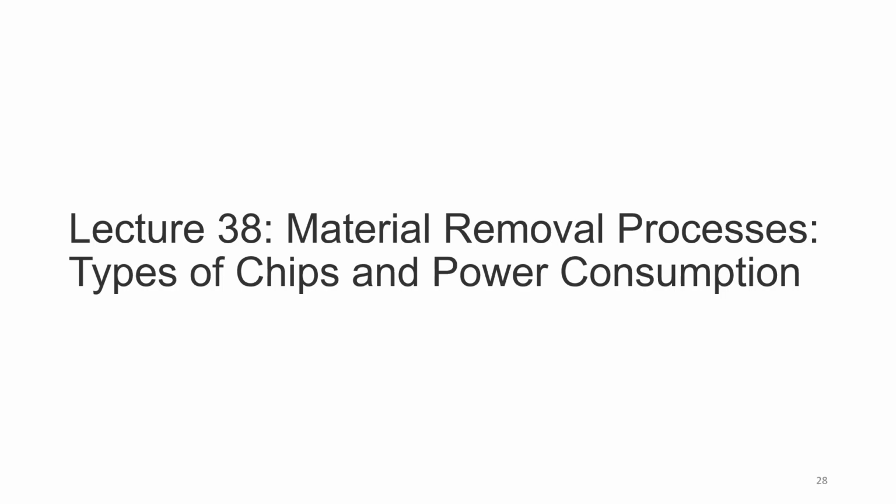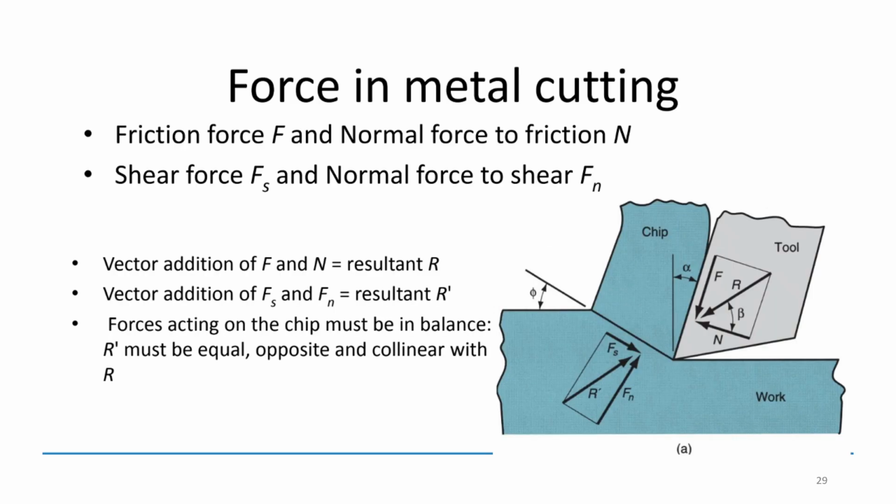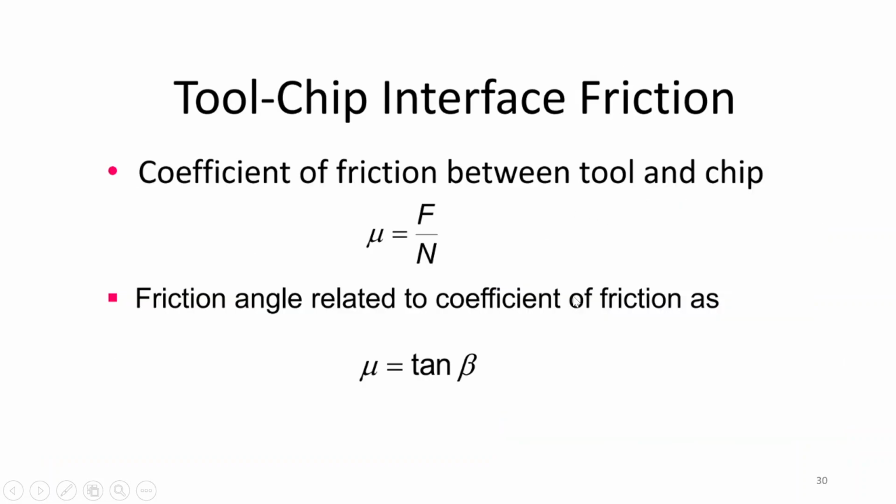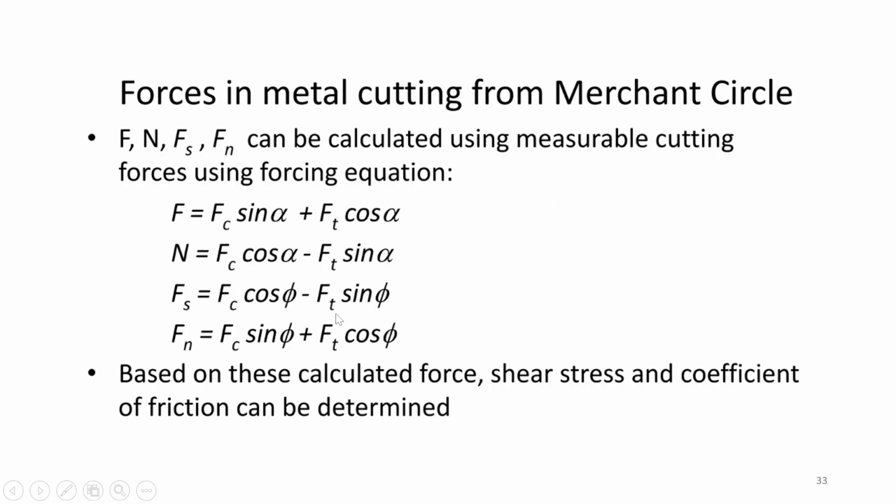Next chapter is material removal process, type of chips and power consumption. In case of forces, we can't measure all forces, so the only forces that we can measure are the cutting force and the thrust force. The other forces that are there, their formulas are given in terms of these cutting force and thrust force.